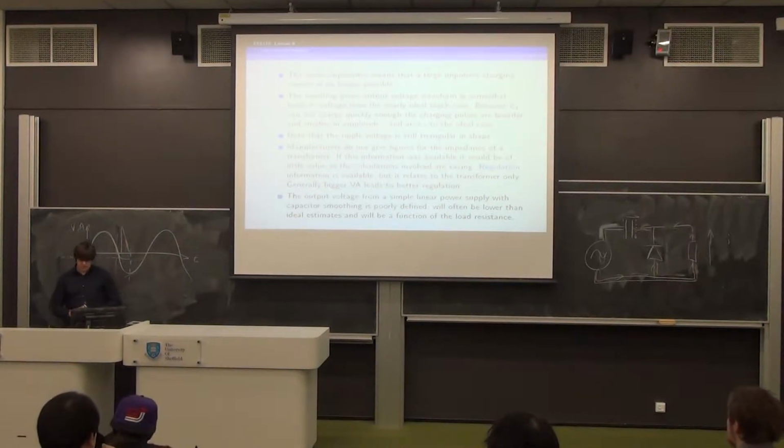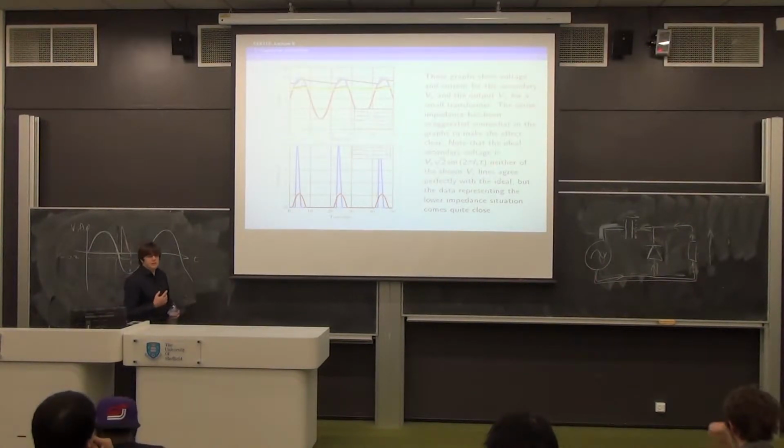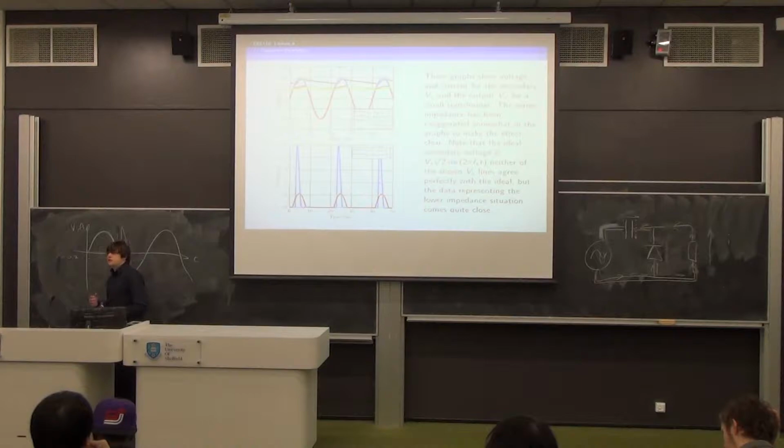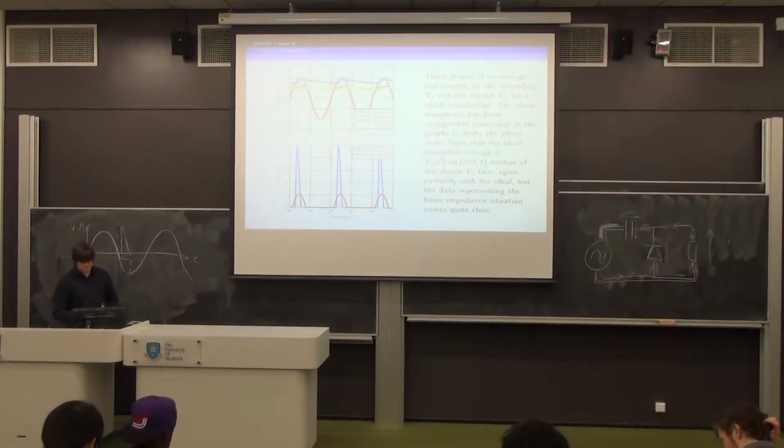The only other things to say is that for the green line and the black line, we can make the assumption for both that the waveform which represents the output voltage has a ripple, and that ripple is still triangular, and we'll use that later to make some calculations a lot simpler.